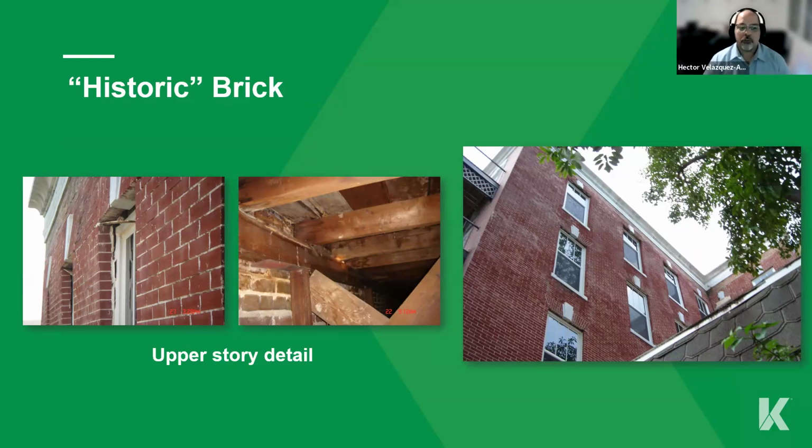Older buildings are going to start showing deterioration on these members, which is what we're going to be talking about, due to water penetration or water issues. If you see the picture to the left, the sealant of your windows starts to detach or break apart, which typically happens in 5 to 7 years, depending on the sealant you're using. You're going to start getting water into your structure. Water into the structure will damage the bones of the structure. Wood framing is very susceptible to that and continues to deteriorate.